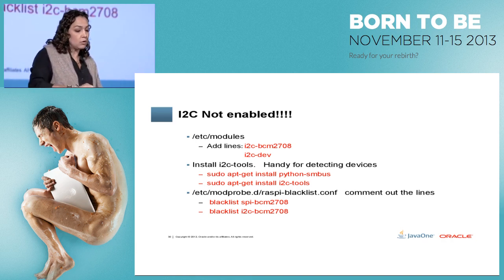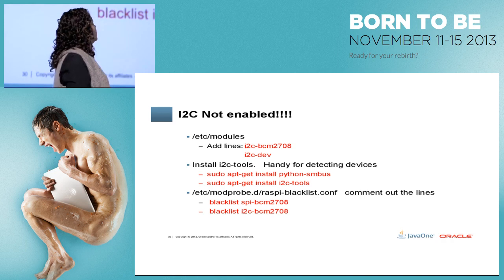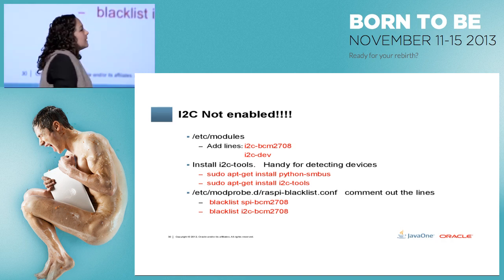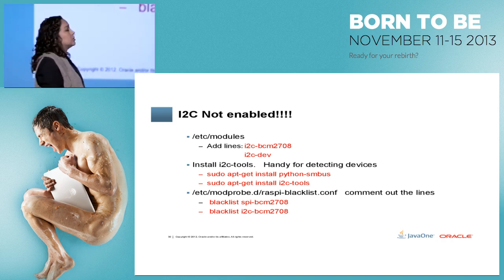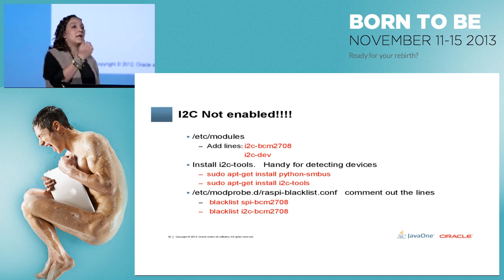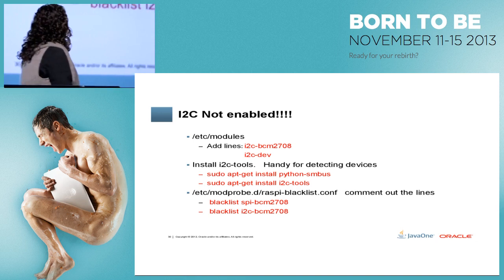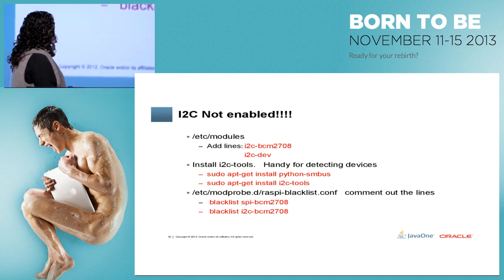Inside the Pi, in /etc/modules, you have to add those 2 lines so you can actually use I2C. It's handy to install i2c-tools. It's not required, but for me it comes very handy. It allows you to see if you are actually detecting the devices. I think it was extremely powerful.